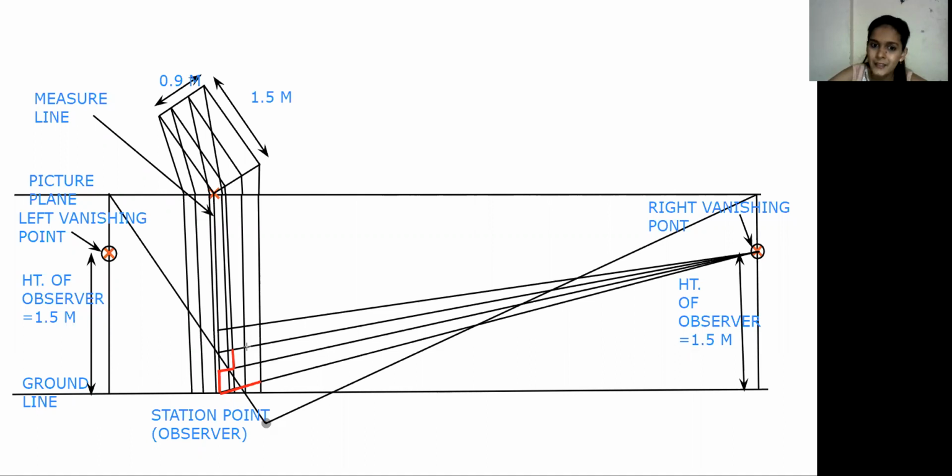Again tread on inclined line. This inclined line between these two vertical lines. Okay. So draw the tread. Again, riser on a vertical line, same vertical line. You can easily identify now. Okay. Then a tread on an inclined line like this. And join this by a vertical line.